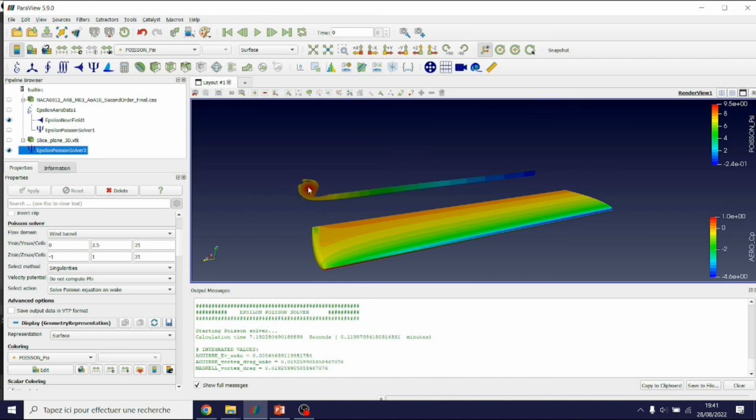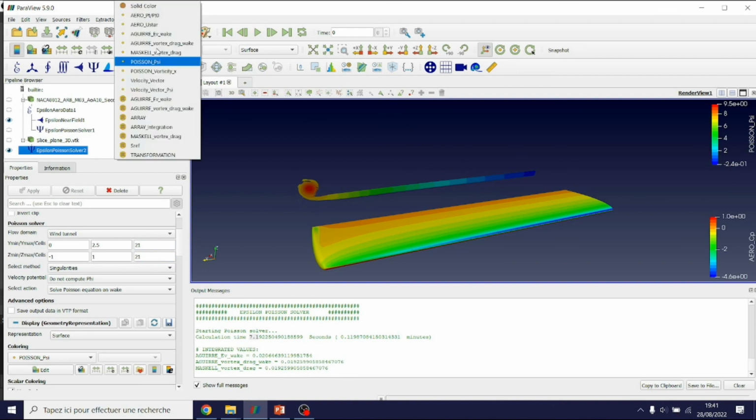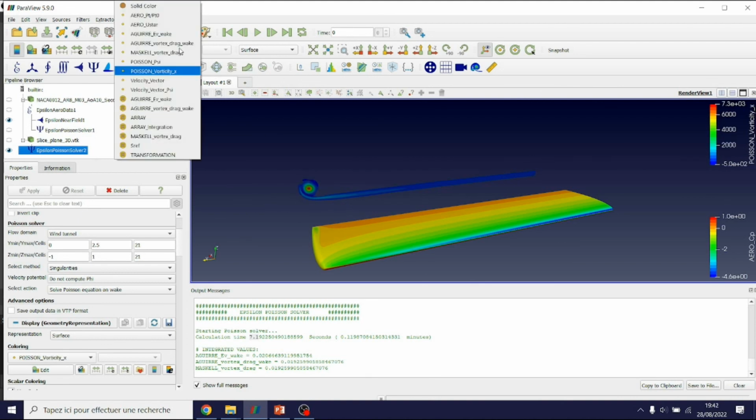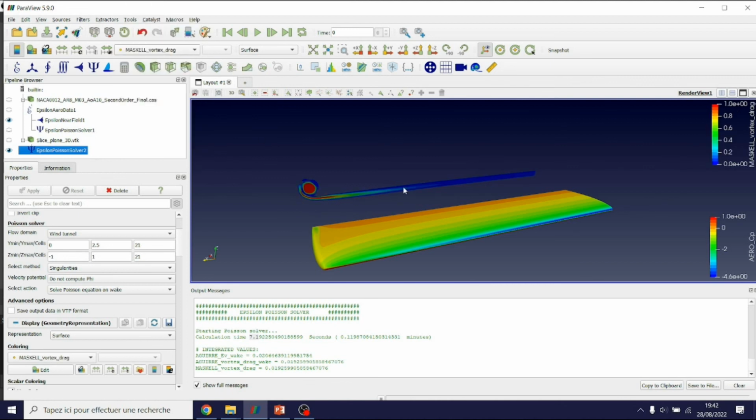And voila, that's the case. You can see I started with 20, it hasn't worked. I changed that to 21, I relaunched it very rapidly. In 7 seconds it has computed, and now I have my stream function at each point inside the wake. Of course, I also have the vorticity inside the wake, and the product of both fields will give me the vortex drag density, like here, masked vortex drag as before. And this is the quantity that's actually being integrated.